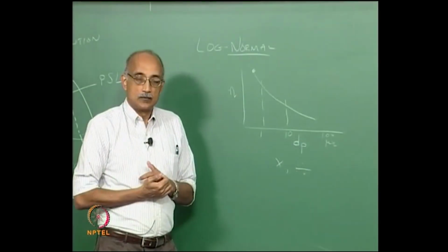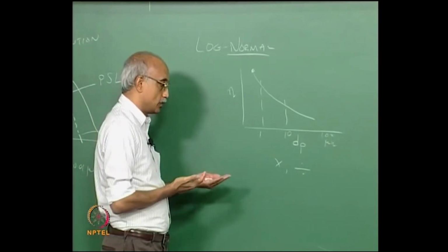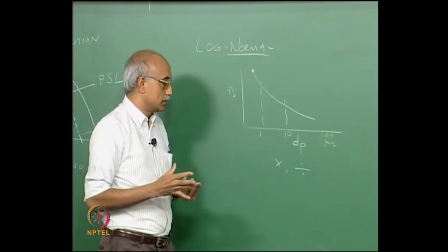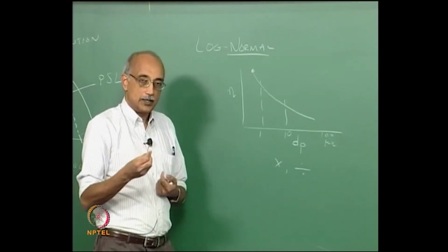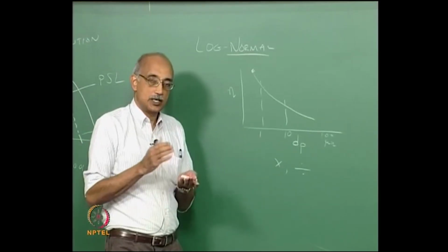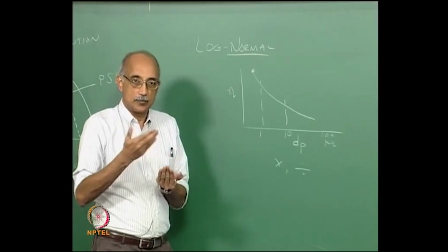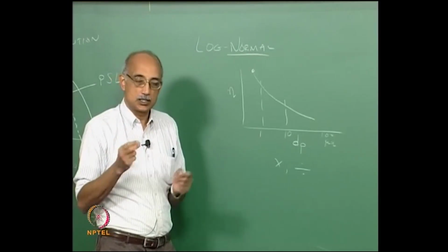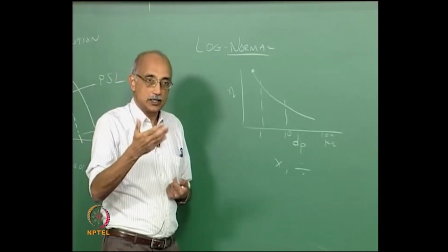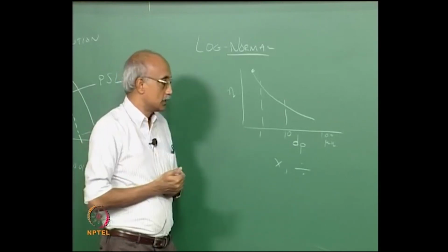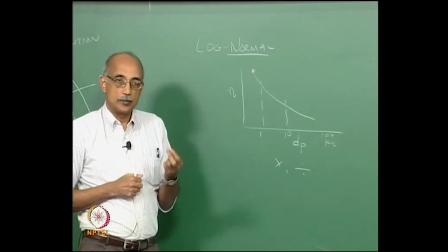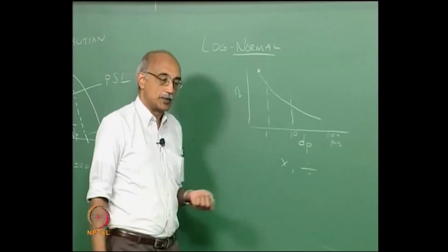Abrasion. When you take a surface and abrade it with another surface, the number of particles you generate is again going to be fairly large in count, and this happens because you are taking a previously continuous surface and abrading it to form finer particles. So, you are essentially taking a large mass or volume of material and dividing it into finer fragments. These are the two primary contributing phenomena to the formation of a log normal population.